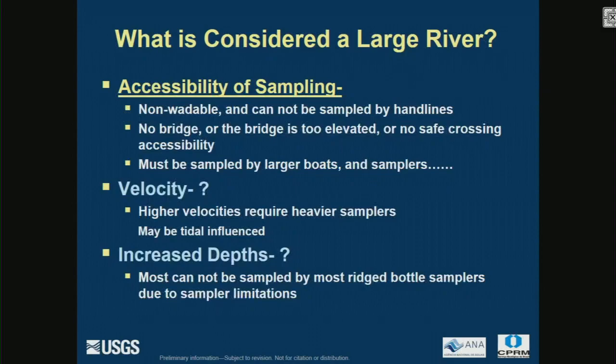The velocity sometimes can be much higher, which requires using larger samplers that you can't use in smaller boats. And we also have increased depths. Because of the increased depth, we're having to use these collapsible bag samplers or flexible bags.